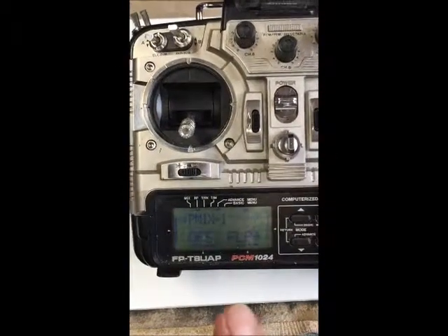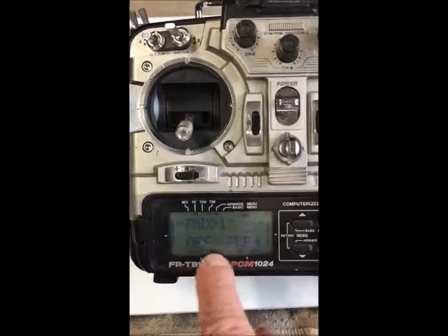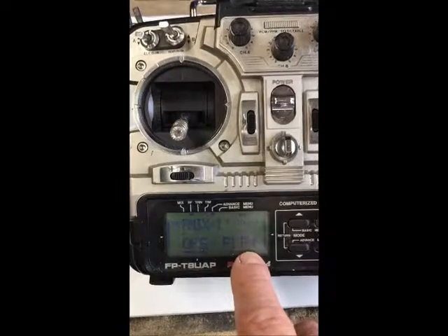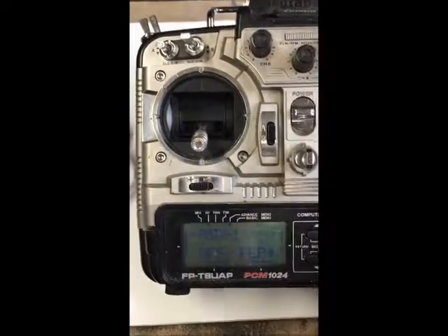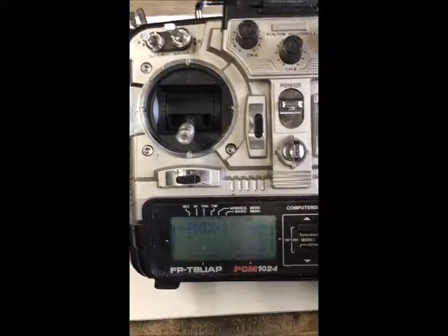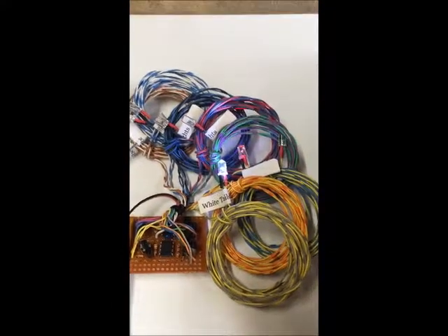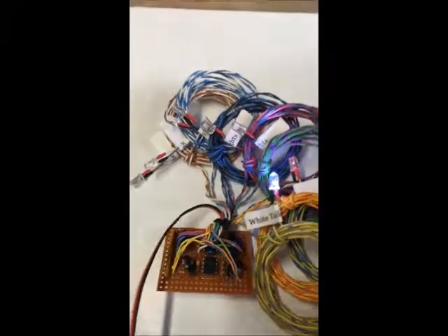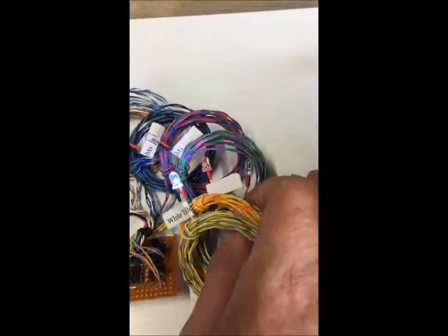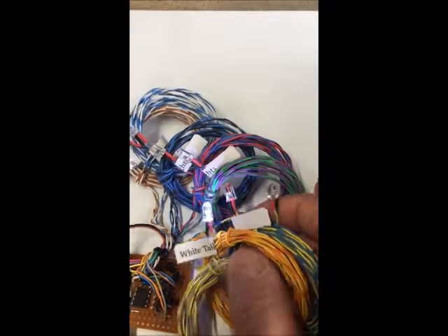You will need 3 mixes. The mix will use the offset function, and you're mixing the flap channel, activating the flap channel. The first mix will need to be at about 60%, and that will allow you, when you turn the radio on, or when you turn the plane on, to have the simulated rotating beacon, the fuselage strobe, and then your white tailcone light.